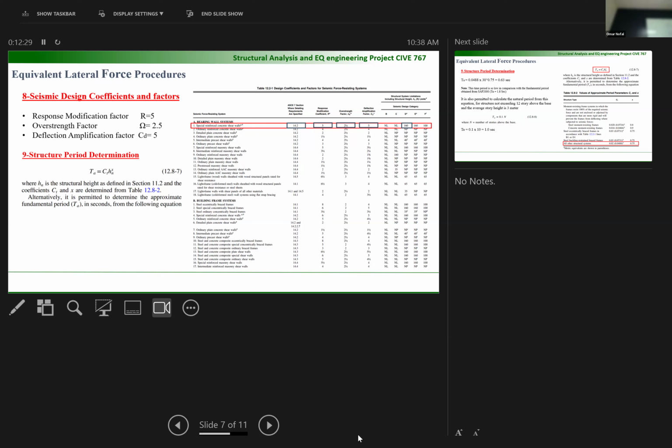Can you imagine? Sometimes R equals 5. Like let's say without R, you are gonna have 1,000-ton base shear in the building. But if you allow inelastic forces, you are gonna make this base shear 200. Can you imagine how much the cross section is gonna be decreased, 5 times? Okay, it's not linear, but I'm telling you, it's like a 5 times reduction. So we call R the ratio between the F elastic and the F inelastic. Okay, so that's the concept of the reduction factor.